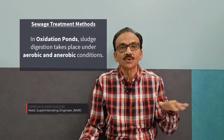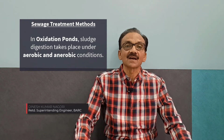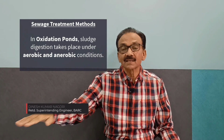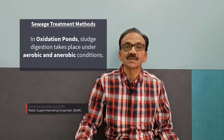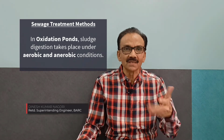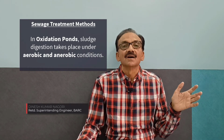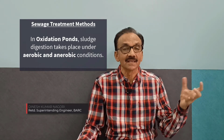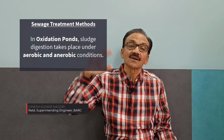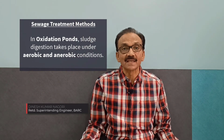See, the surface is open to sunlight and algae plants are there, so the oxidation of sewage takes place with the aerobic system, and in the bottom layer, further treatment, sludge formation and digestion take place with the anaerobic system. So both systems are working, but there are many advantages and disadvantages of every system. Like an oxidation pond, you need a lot of space. Then in the rainy season, it doesn't function properly. Sometimes foul smell may come, so you may have to construct the oxidation pond far away from your building. You may not have that much area.